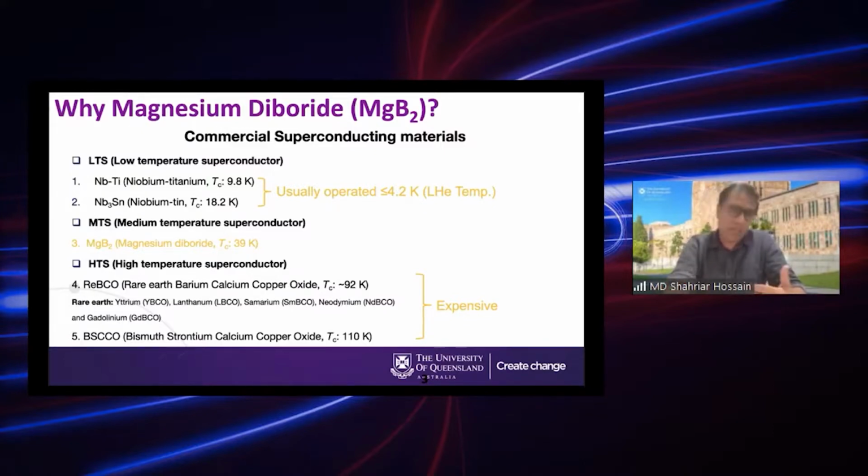But the motivation for MgB2 is liquid helium free application, because liquid helium is getting more expensive day by day. And for niobium titanium, another problem is the Tc of 9.2K. Cryogen free operation is really difficult because the Tc margin is really low. With 9.2K and 4.2K, this is very risky for the application.